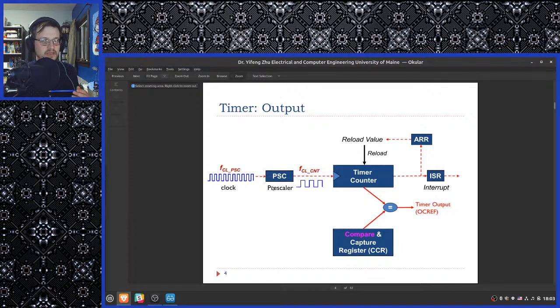It's also incrementing up to some specified value, except instead of having all of this stuff going on, all it does is output the rising and falling edges according to its count, which is then read by the timer as its clock signal. So it's like a timer to a timer, in a way. So is the point of prescalers just to slow down the frequency of the clock? Yes.